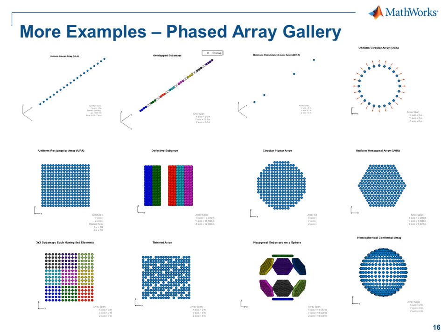Radar engineers work with common antenna array geometries, such as the uniform linear array and the uniform rectangular array, but also arbitrary geometries as we've seen today. Here are a few examples of linear, planar, and conformal arrays and subarrays generated with the product. Another important characteristic of an antenna array is the radiation pattern of the individual sensors. The toolbox lets you specify your own custom element response using either analytic expressions or measured data.